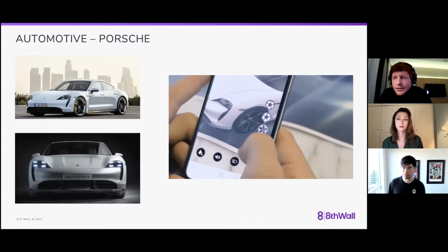And the second one is the textures. If you're creating materials for offline rendering, you can have basically a separate texture set for every single material on your model. So you can have like 10 texture sets, each can contain like 4, 5, 6 textures. But if you want to create a real-time asset, you should probably bake them into one texture set, because first of all, you reduce the size tremendously, right? Imagine you have 10 4K textures times 5, so like 50 4K textures, and instead of that you should have like 4 or 5, and preferably 2K.